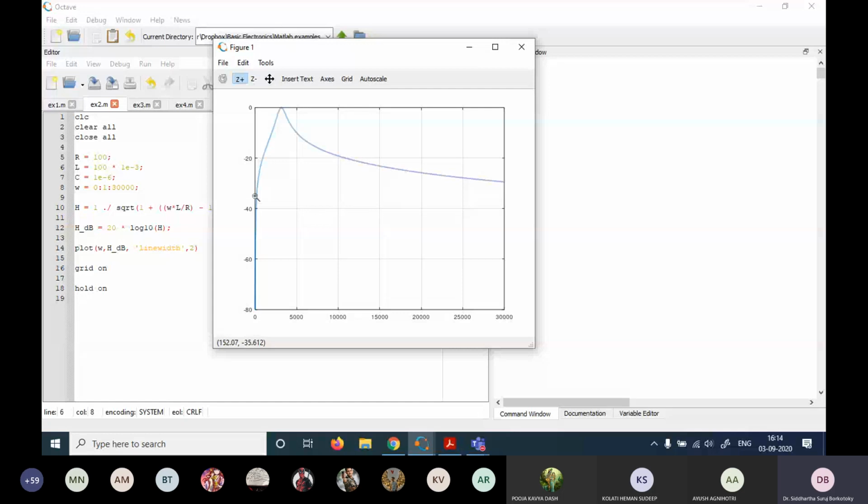You can plot one output on top of the other. So just like before, you could take this and plot it for different values of R, or maybe for different values of L. Keep changing these values and you will see the pattern in the variation, how these things change. I guess this is the basic main strength of simulation tools like Matlab and Octave. So you could easily write down these equations.